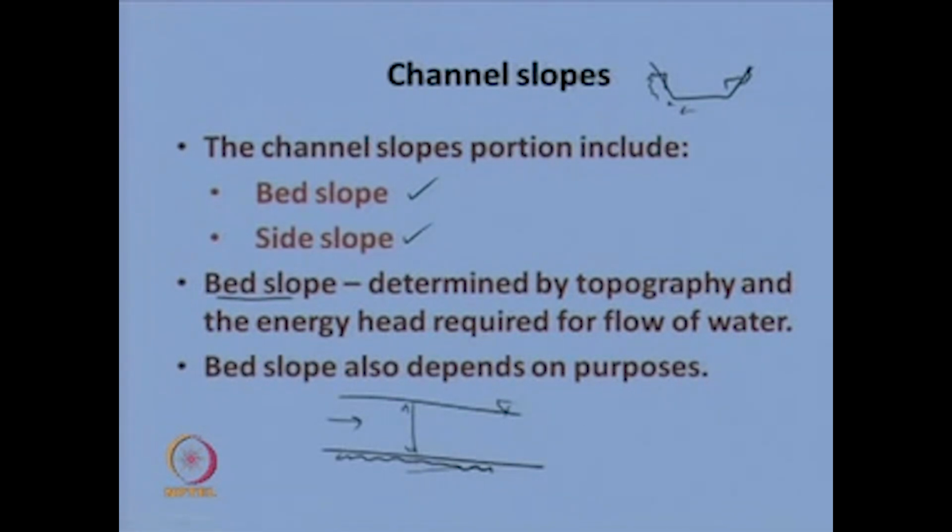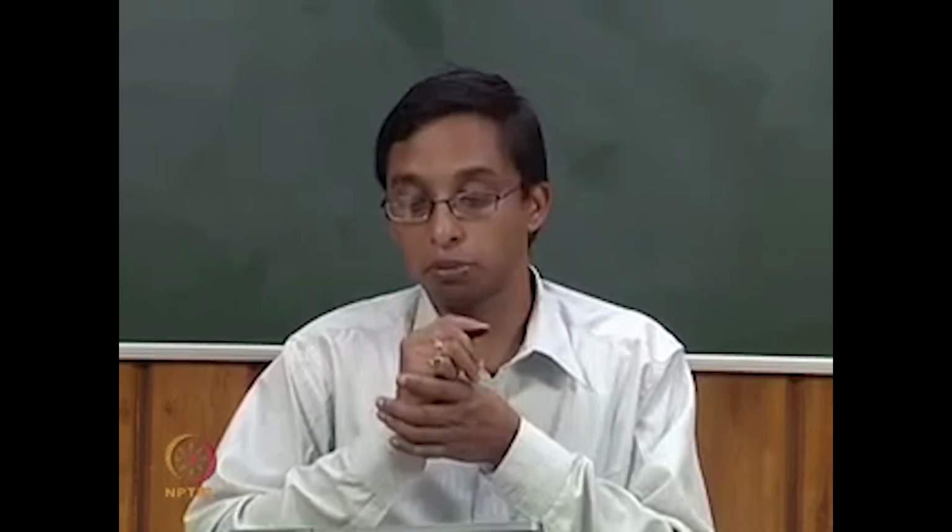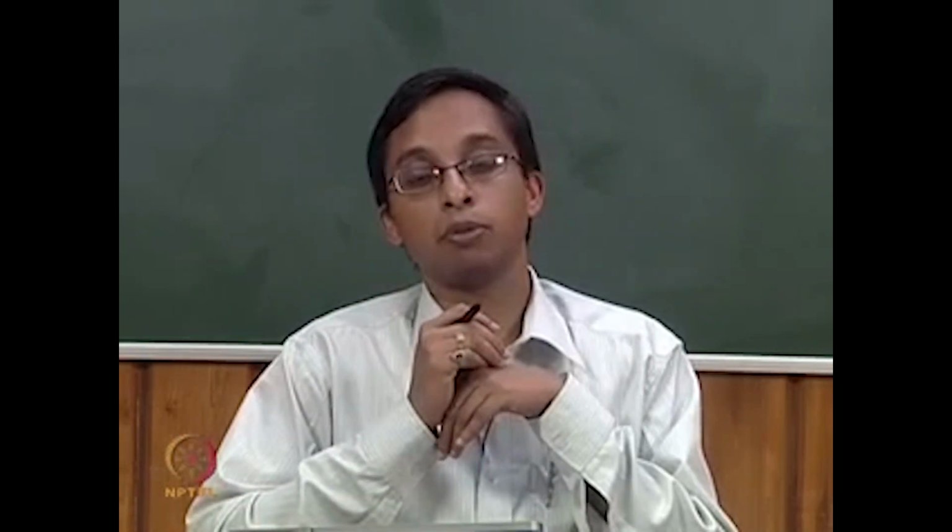The bed slope also depends on various purposes. Say for example, if there are multiple projects, irrigation projects or hydraulic power projects, the water at the entry of the channels for irrigation purpose as well as hydraulic power projects should be at quite higher elevation.